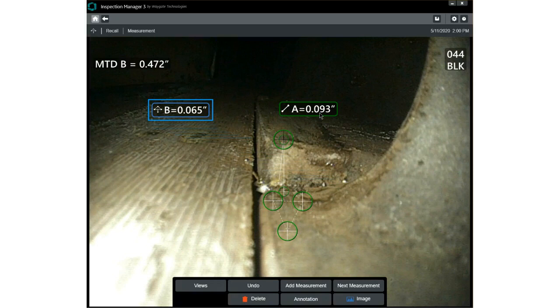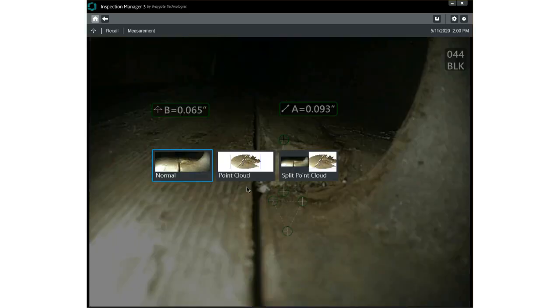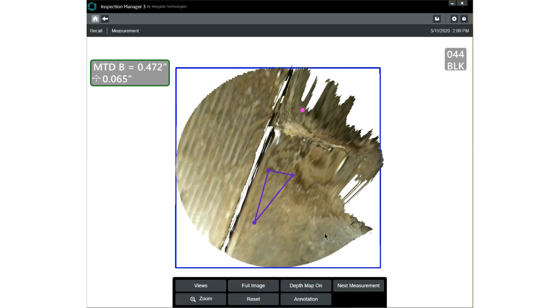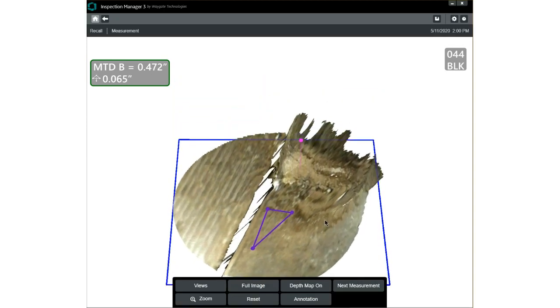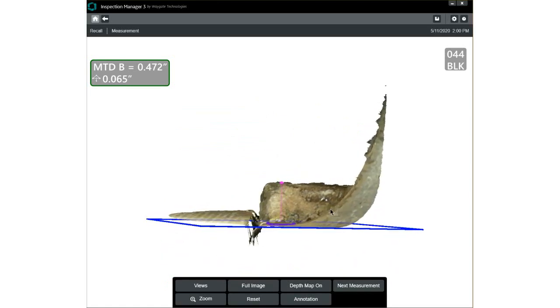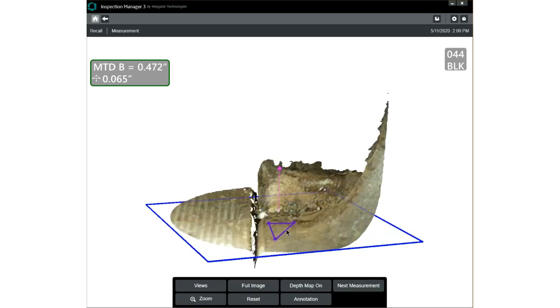However, I haven't called anything yet. I'm simply telling you I have a 65 thousandths of an inch measurement with this data, and I will look at the point cloud in the full point cloud view. The first thing I will do is look at the data that's on the near side stator floor. I want to make sure that all of these 3 points are on that flat part of the stator floor. They have not started